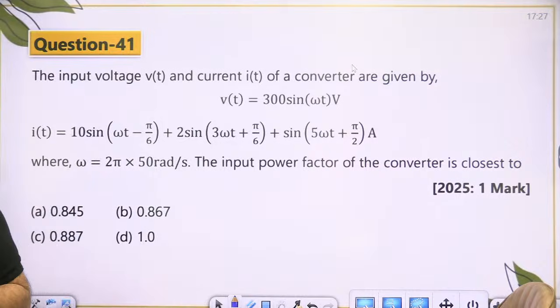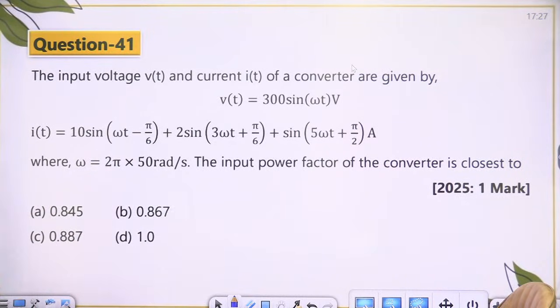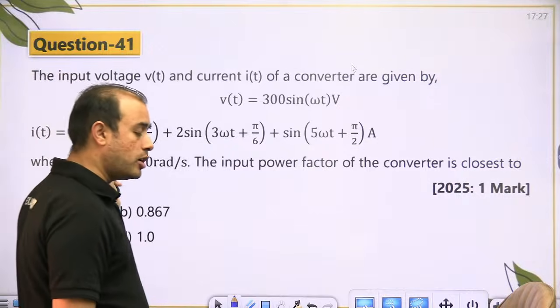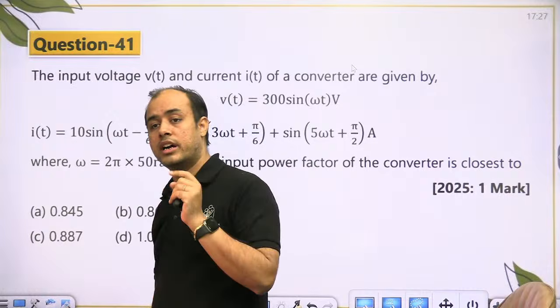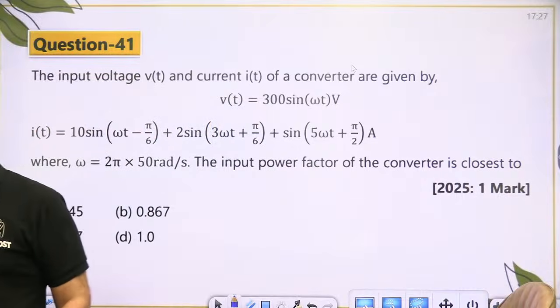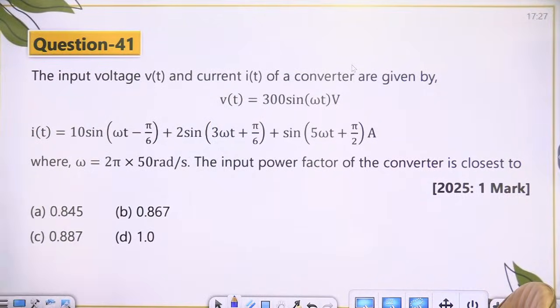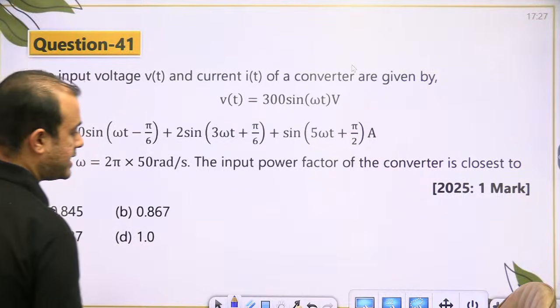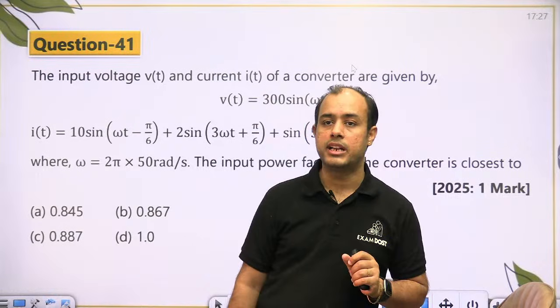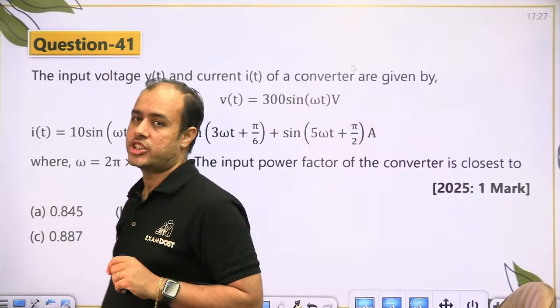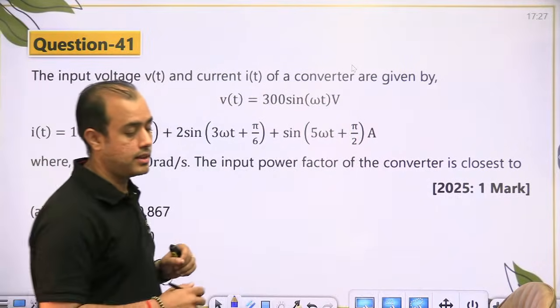If I want to convert torque to current, but I do not know how to do it, then from EMF I can find Km phi and use that to convert torque into current. Logic समझ रहे हो? अगर मैं EMF से और स्पीड से Km phi निकाल लूं और मुझे सवाल में टॉर्क दिया है तो मैं टॉर्क से करंट बना सकता हूं. ऐसी सिचुएशंस में वो हेल्पफुल होता है.